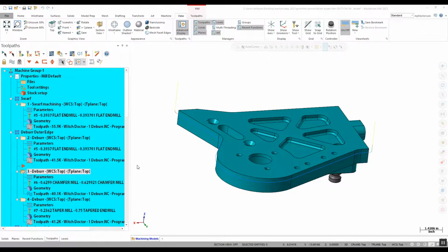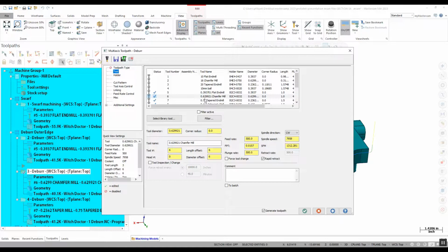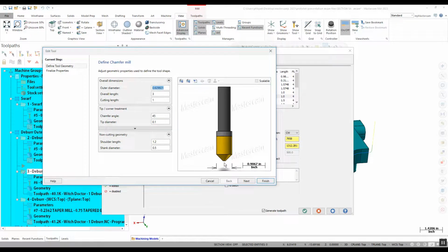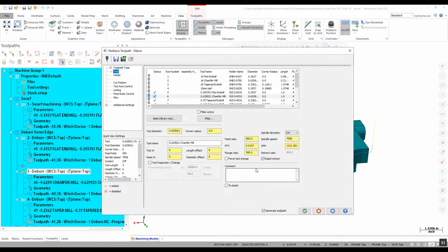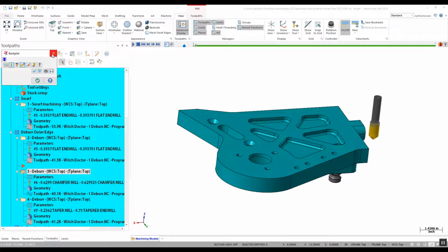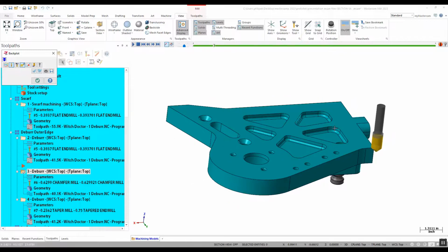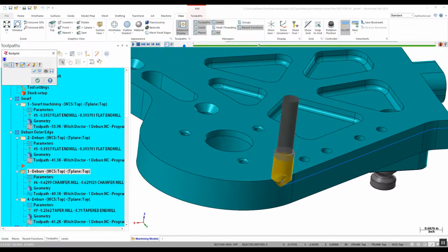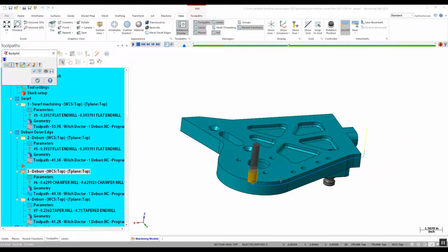Now let's say I want to use a chamfer mill. So if I come into chamfer mill, now I got a 45-degree chamfer mill. Now this is going to turn this essentially just like into a 3-axis toolpath. So same toolpath, just picking a different tool. And now since that's a 45-degree tool, obviously my chamfer mill is just going to work along there, in this case, in a 3-axis motion. But if it had tilt or do any movements while cutting, it still would do that.